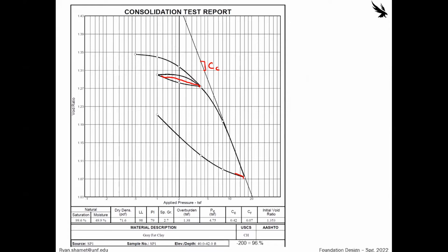And what that means, sorry, I'm going to have to start standing closer to this because I think the audio doesn't pick up very well. But what that means when you're working on predicting the actual field settlement or the consolidation of real soils is we cannot be super accurate. So when you start working as a geotechnical engineer or with geotechnical engineers, providing the anticipated settlement of a project site to 4 millimeters or 0.4 of a millimeter, there's no way we can be that accurate because we're making all these assumptions with our raw data. So I'll show an example here that talks about that.